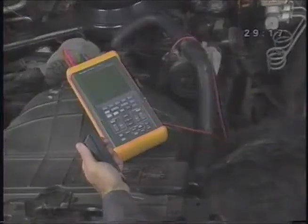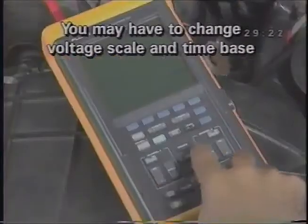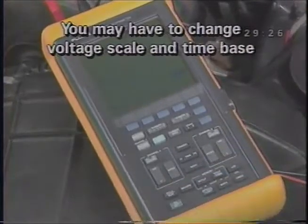Crank the engine. You may have to change the voltage scale and time base, since cranking speed and the number of cylinders affects the voltage level and the time between cycles. Once you have between 1 and 4 cycles displayed, press Hold Run. That freezes the display for detailed examination. Let's see how to use the waveform you've just captured to diagnose an ignition problem.